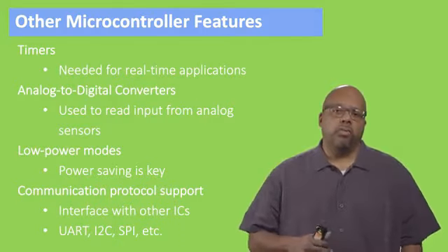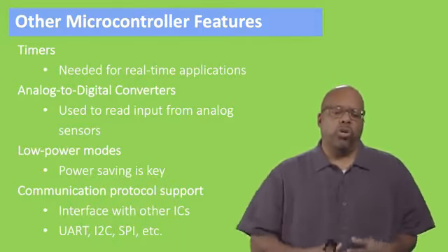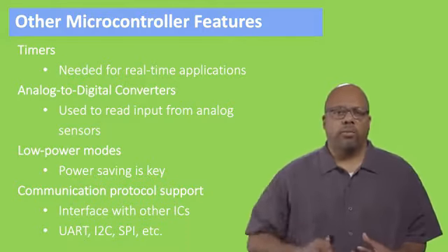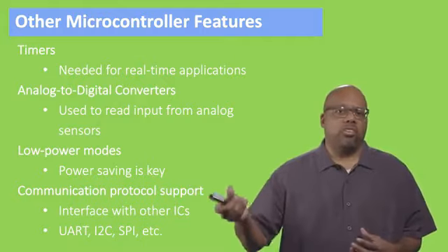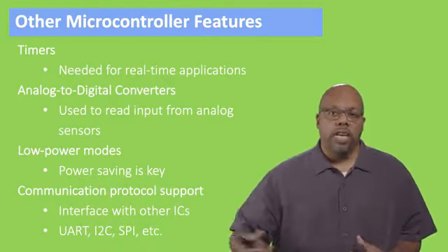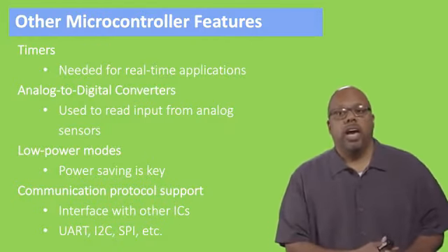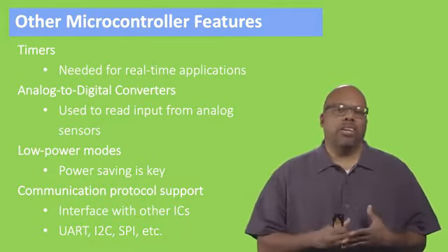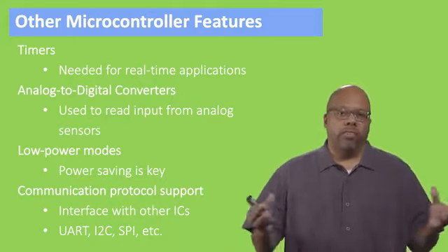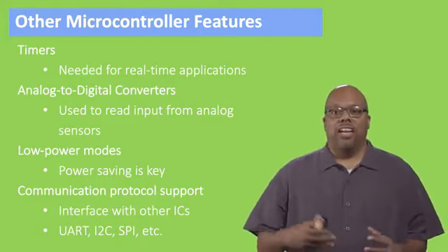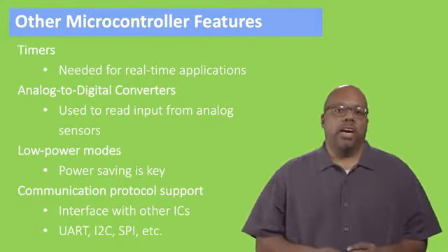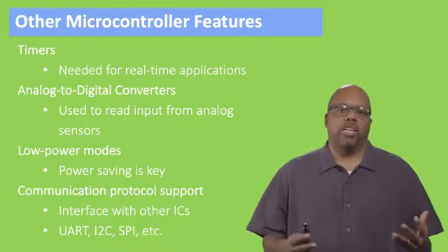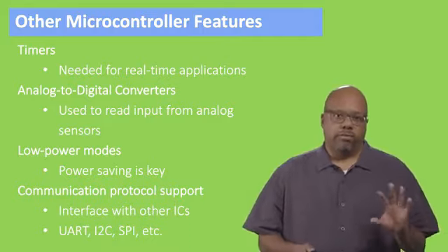Now this is important because when you're making your bigger system, say you want your microcontroller to talk to some SRAM chip, right? This SRAM chip, maybe it talks I2C, but it doesn't talk SPI. If your microcontroller doesn't support I2C, then you have trouble. Now, generally, these microcontrollers nowadays mostly support everything, all the ones I just said, and others too. So in most basic microcontrollers, you have a lot of communication protocol support, but you should check just in case.